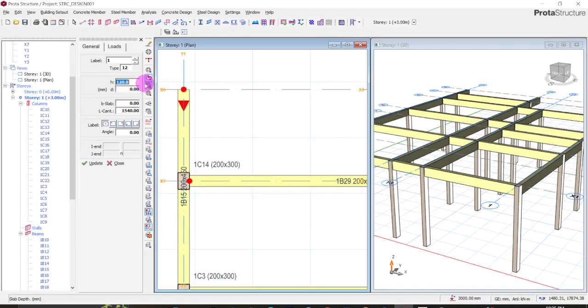and then our height will be 150, and then our loadings will be, you have self weight, and then you have dead load can be 1.5, imposed load can also be 1.5, and then parapet weight. In most cases we use railings, but sometimes we can also use the masonry wall, some dwarf wall on these cantilevers.